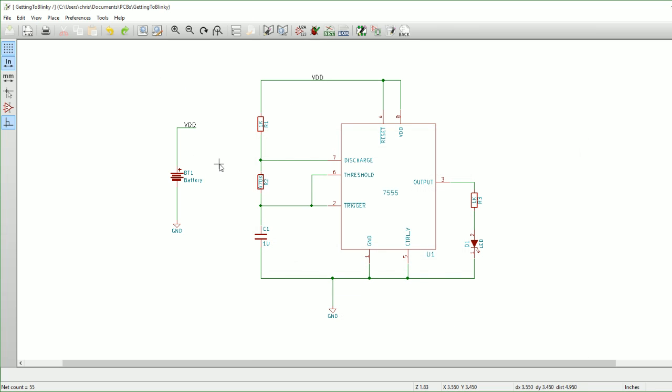Okay, and now we are at the point where we can say, yes, we're ready to go. We're ready to start doing part association. So you can see the schematic is, for small schematics, definitely a simple thing. It's all about making sure your things are connected together and getting your parts labeled using annotation. That's very important. And then some of the more advanced topics that you'll get into, say you took a contextual electronics course, we talk about making sure you have all the information when you edit a component. So do you have the part number in there? Do you have other specifics like a voltage rating that we didn't do here? That's necessary for certain things, but for our purposes right now, I think we're doing pretty good.